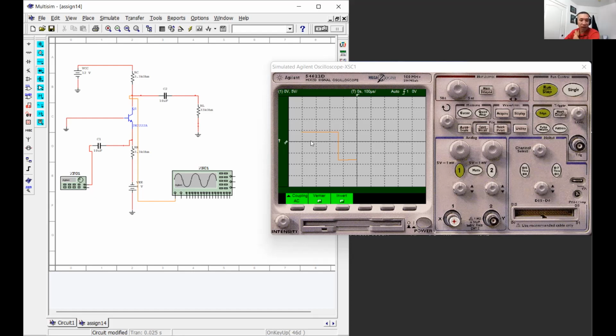And then finding the problem is going to take a little bit longer because we have to erase a lot of these wires and reconnect them. Okay. So the key is to keep it clean while I'm going through and testing. Yeah, just minimize the number of points and connections you have to make. I'm supposed to use AC coupling for this, right? Yeah, you want to stay with AC coupling because we have an AC signal coming through. Okay.